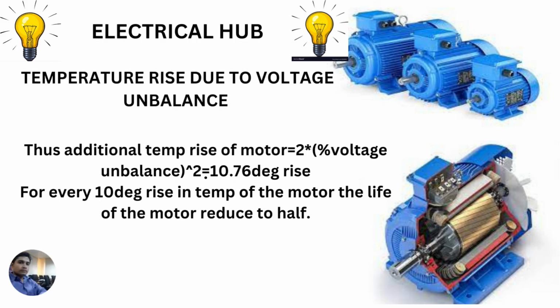Here we will calculate the temperature rise of the motor due to the unbalance in the voltage. The additional temperature rise of the motor is equal to 2 into the square of the percentage of voltage imbalance, which is equal to 10.76 degree rise.